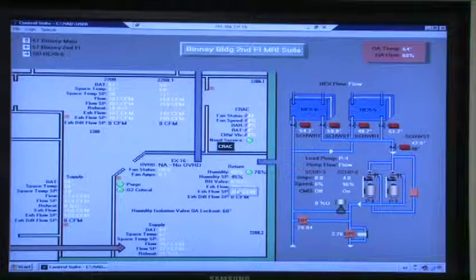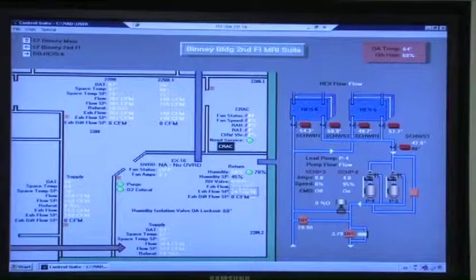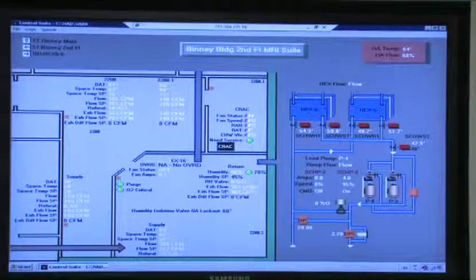If the damper is closed, you're not going to have any change across the measuring station, so it should go to 0. So what you should see is the exhaust fan command to on, which you'd have to assume means the damper opened, you see amperage, and you see the return here go to 0. So no more return flow.